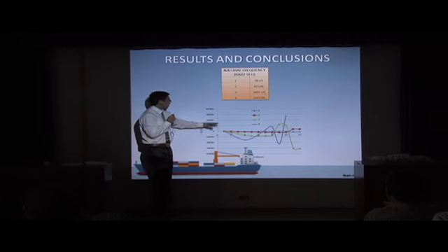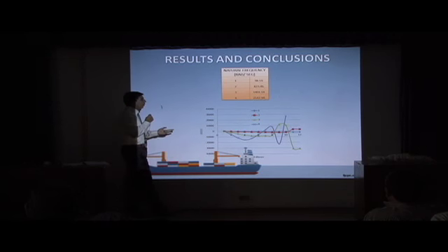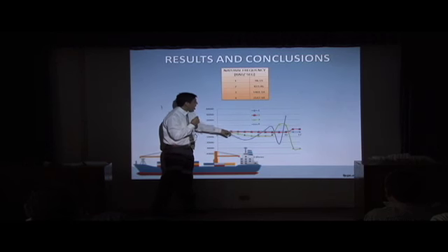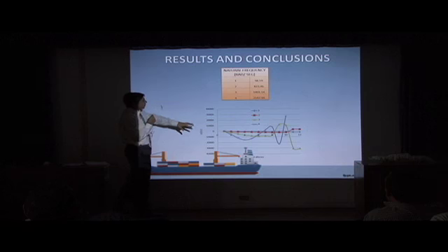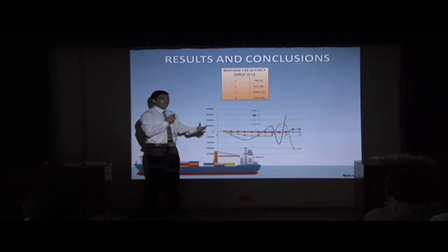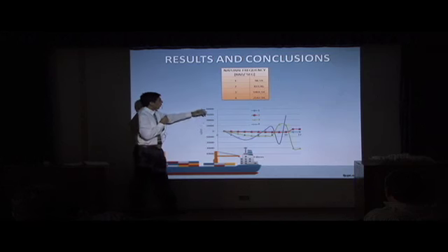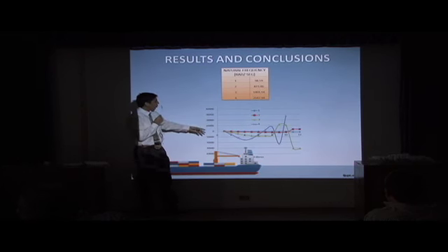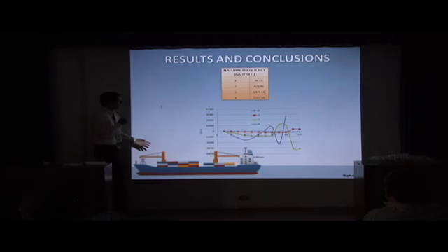We can see that the first mode has only one change of sign, the second two changes, the third three changes, and the fourth four changes of sign. This model we use to determine what the frequency is. For example, in the fourth frequency, mode 4, we have 4 changes of sign.